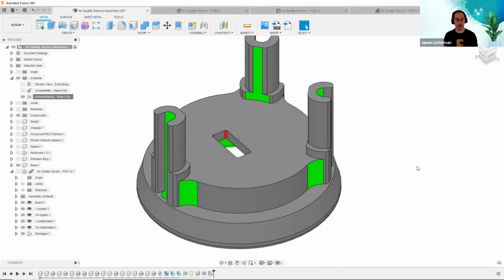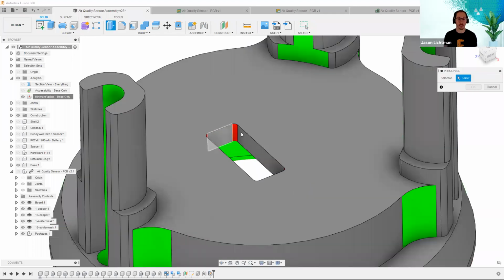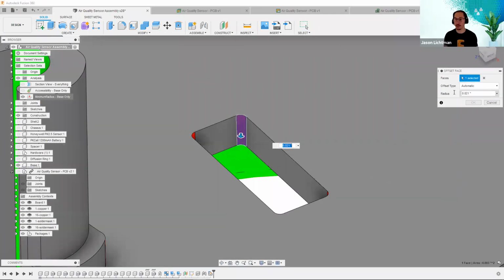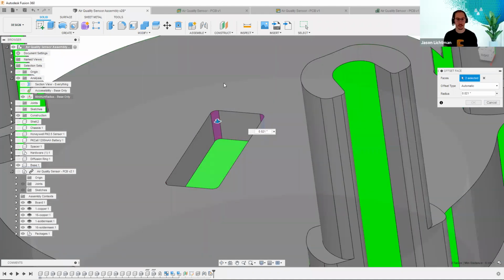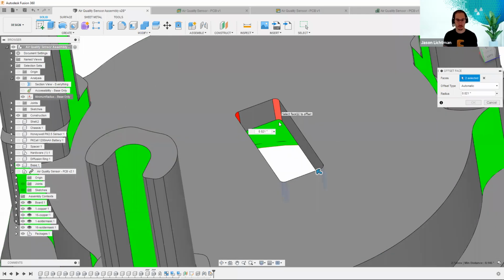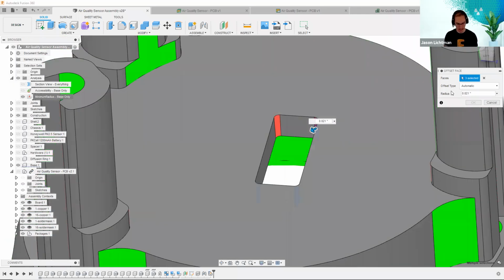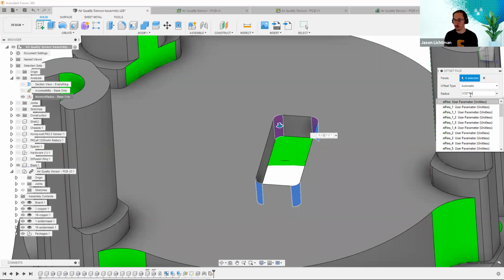So in this case, I'm going to make the quick change to that radius over here that you mentioned. Right now it is 21 thou. And what was the minimum that you said? So about a 32nd of an inch is going to be a right minimum radii. So let's go and do this. And I want to do all four at the same time, so I'll go and select those. Cool. And we're going to go with 1/32 of an inch. Let's go and do that.